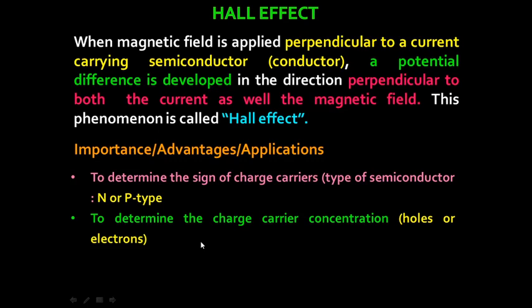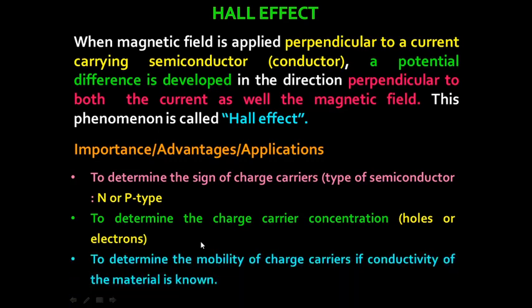The third important point is that the Hall effect is used to determine the mobility of charge carriers, means the ability of movement of charge carriers can be easily determined by the Hall effect if the conductivity of the material is known. So these are the importance or advantages of the Hall effect.